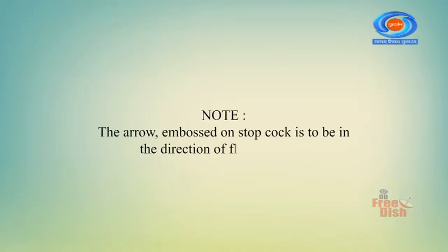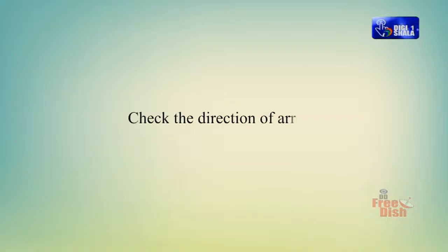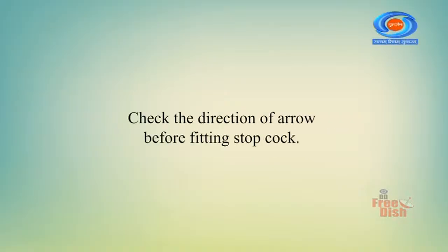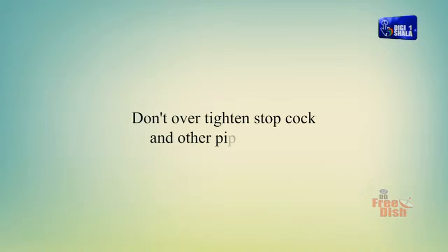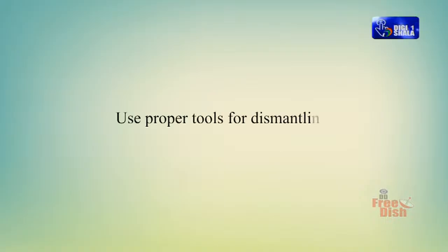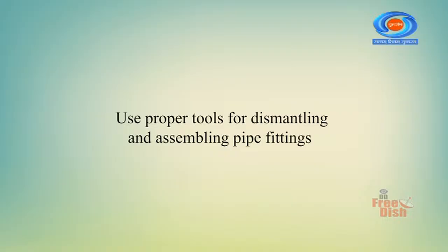Note: the arrow embossed on the stopcock is to be in the direction of flow of water. Check the direction of the arrow before fitting the stopcock. Don't over-tighten the stopcock and other pipe fittings. Use proper tools for dismantling and assembling pipe fittings.